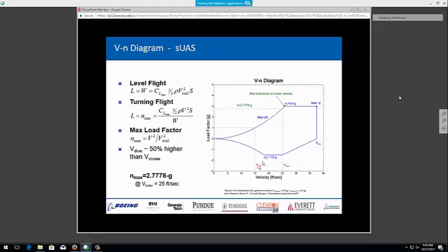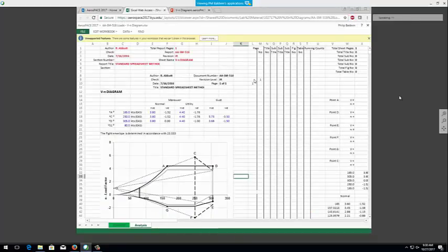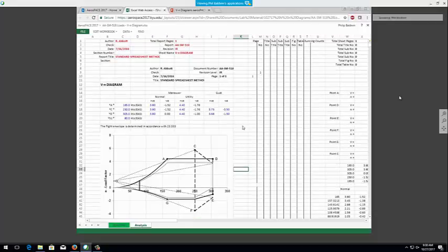The numerical integration is also not adequate, but fortunately, MATLAB is here, and we can define a different derivative method with a very explicit first set of first-order differential equations, where your position derivative is your velocity, and then your velocity derivative is your net thrust over mass. These are the exact same ones to look at a trajectory in x, y, or you could call it xz space for a launch.